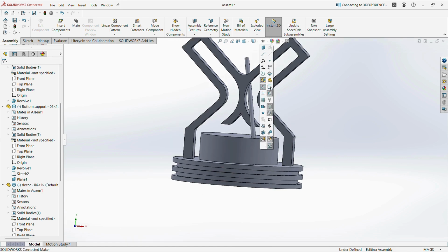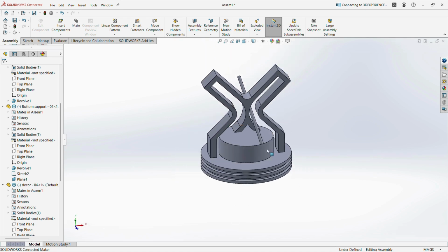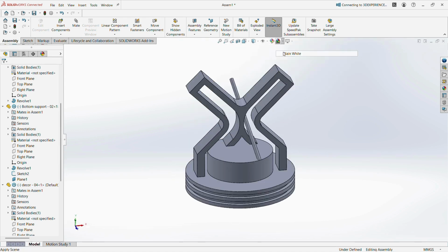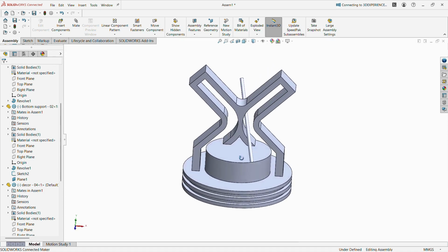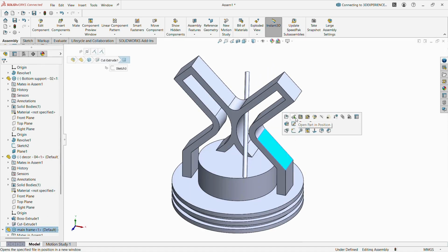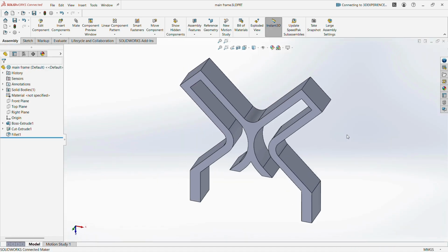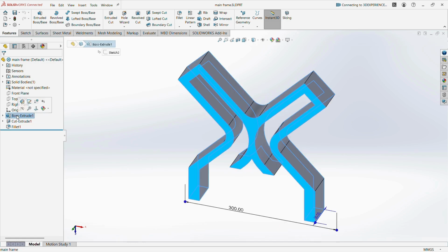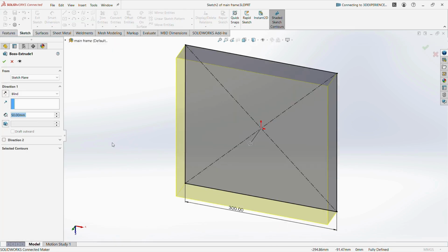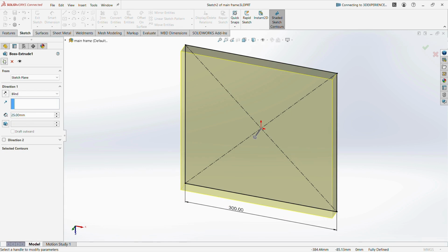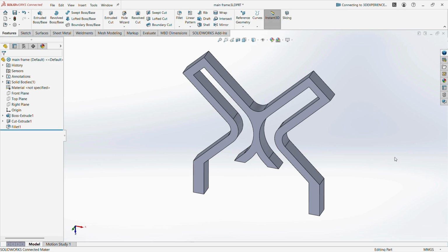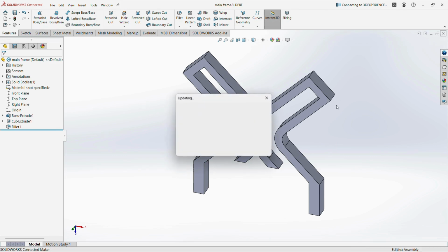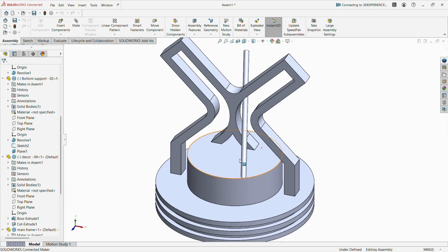we are going to edit the features. Almost it is 50 mm. I am going to edit these features with a new 25 mm thickness value. So selecting this particular solid body, open the part and choose this particular position under boss extrude. Then change the value to 25 mm. Otherwise, it collides with each other and causes interference detection. Almost we complete the entire assembly right now.